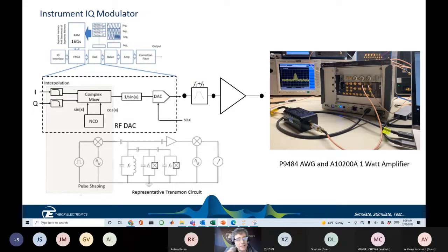Let's look specifically at the DAC system of the instrumentation. A regular arbitrary waveform generator has some kind of RAM system, and you would have segments, and you play different segments in different orders, and that would all be orchestrated by the FPGA, and you would play out through the DAC.